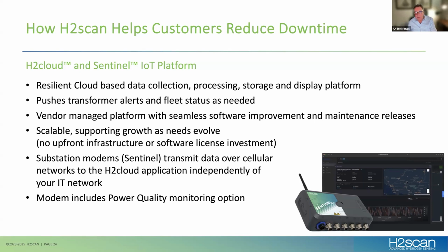If you're not sure about harmonics, just think, harmonics are generated if you've got a lot of switched mode power supplies, think a lot of chargers in your factory. If you've got a lot of variable frequency drives, or if you've got your own connected renewable sources of energy, they all create a significant amount of harmonics. In my experience, harmonics are often misdiagnosed as the transformer being undersized, or the transformer's design being poor or built poorly, when in fact it's just the presence of a lot of harmonics.